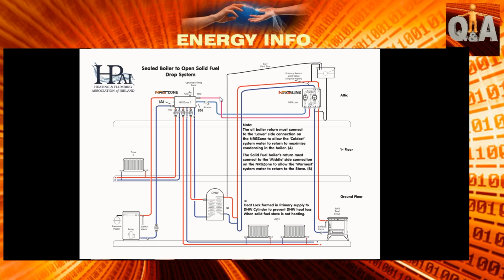I do understand that there's a safety valve next to the solid fuel, but you cannot rely on a mechanical valve to keep people alive or safe. So you have to have an open, completely ice-free solid fuel circuit. The gravity circuit there is critical that it's insulated extremely well for two reasons. The minor reason is that it's going to keep energy. The major reason is that it keeps people very, very safe in cold conditions.